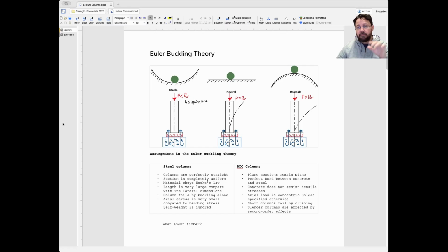Even if you make a calculation and you say, the maximum axial load that this column can resist is this much, with half of that, if you put it in the wrong position, it fails. So they were realizing this. How is it possible that columns with axial forces of smaller value still fail? Well, because this is not a problem of the magnitude of the force, but it is a problem of the point of application of the force. Hence, there's a problem with equilibrium of it.